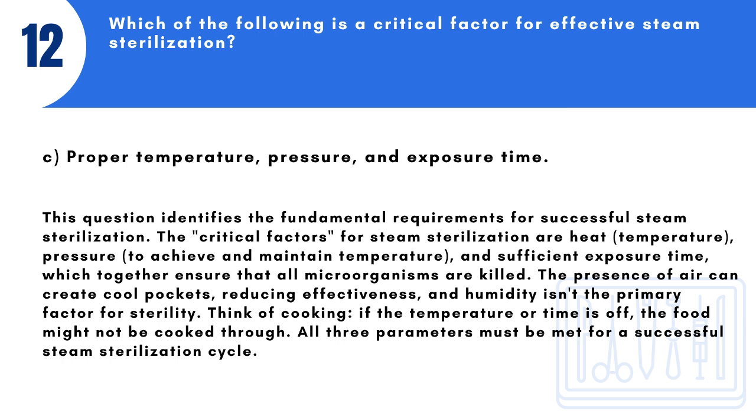The presence of air can create cool pockets, reducing effectiveness, and humidity isn't the primary factor for sterility. Think of cooking. If the temperature or time is off, the food might not be cooked through. All three parameters must be met for a successful steam sterilization cycle.